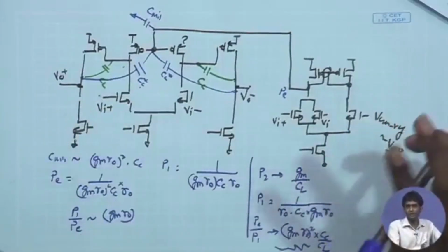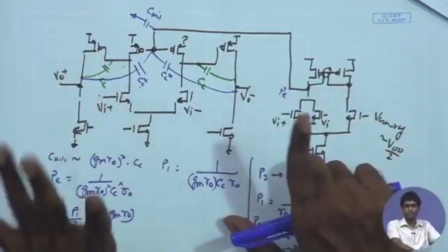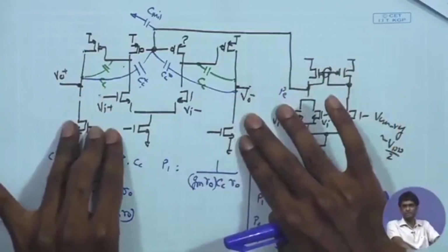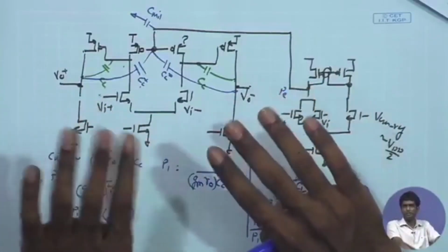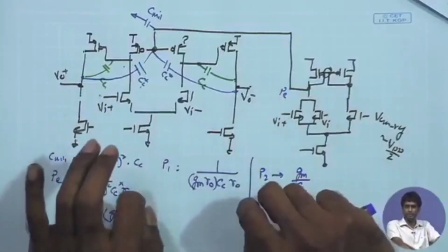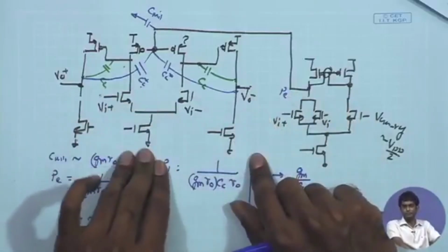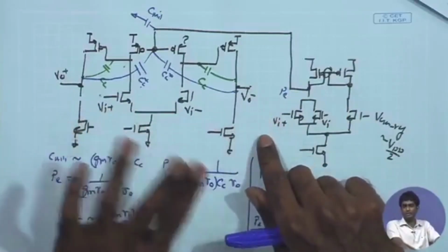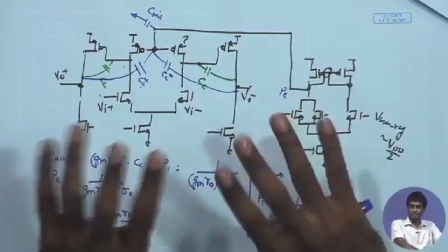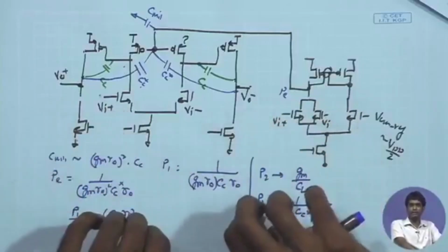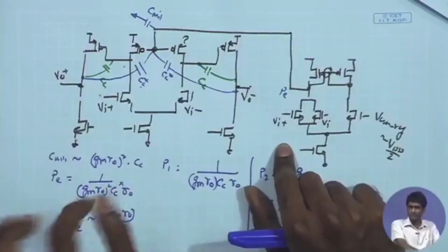So, in general for calculations we will be using the second order model, which is not very accurate, of course. It just gives you a starting point, that if you have estimates of the device parameters, or you have the values of the device parameters given from the technology, like the K and Kp of the MOSFET, the noise parameters of the MOSFET, the lambda value of the MOSFET, if you have these parameters given, or even if you can estimate these parameters, like in the second order model we use just lambda VDS, and that lambda is not explicitly mentioned in the higher order models. It depends on many other parameters. So, in order to extract the parameters that you use for second order calculation, you can do a DC sweep on your MOSFET and extract what is the effective lambda.